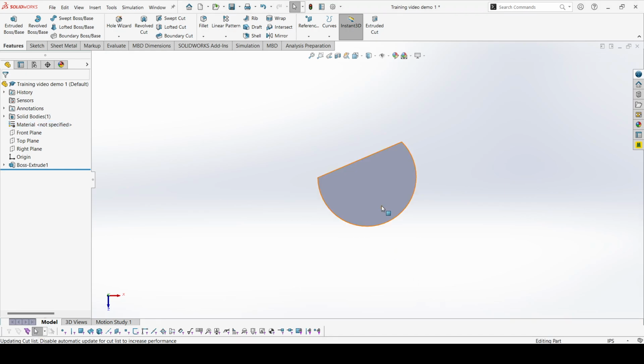When you don't have a specified material, you'll see it's this color. Our most common material is 6061, so we're going to go to aluminum alloys, and it is called 6061-T6 SS. And no, this has nothing to do with Germany, don't worry about it. We're going to hit apply, and then close.